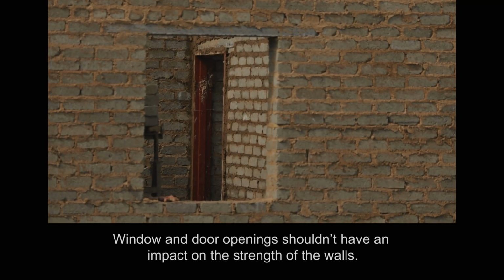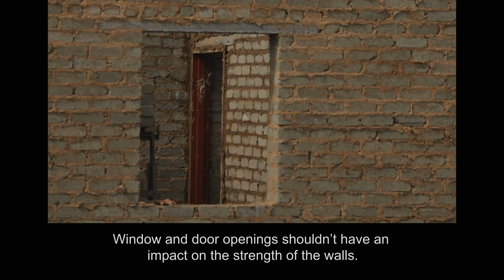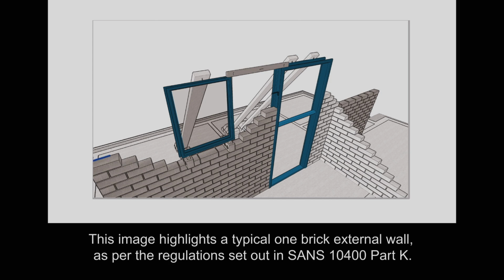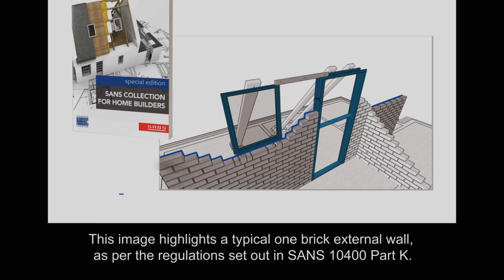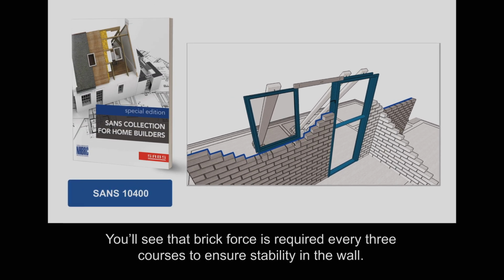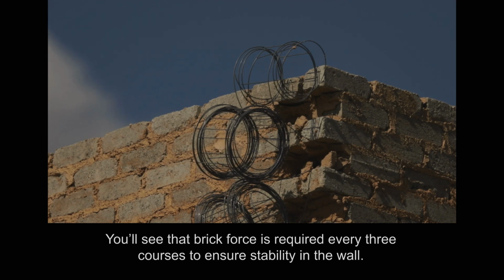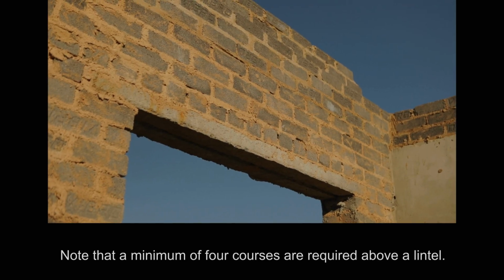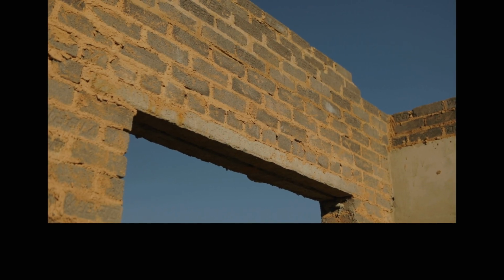Window and door openings shouldn't have an impact on the strength of the walls. This image shows how windows and doors can be built into a wall correctly without affecting the strength of the wall. This image highlights a typical one brick external wall as per regulations set out in SANS 10400 Part K. You'll see that brick force is required every 3 courses to ensure stability in the wall. Note that a minimum of 4 courses are required above a lintel.